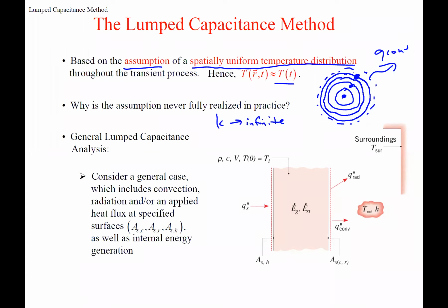Right? It has thermal energy moving through conduction so fast, because it's infinite, that there's no temperature change through that sphere. Well, we're still going to be able to make that assumption in some cases where it's still relatively high, because right now we have this conduction going through here, that's Q conduction, but we have convection on the outside.